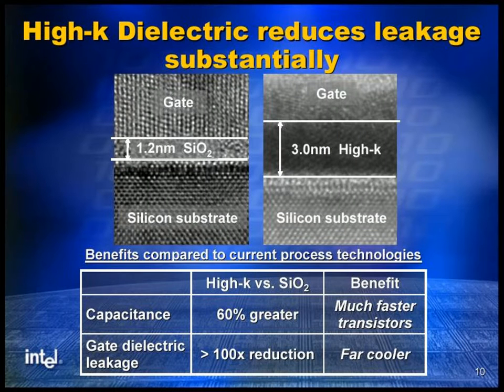What happened, actually we already discussed it. The main thing that happened that was not yet there in the document of 2001 was this introduction of the high-K dielectric process. And you see the situation from a thickness of 1.2 nanometer of silicon oxide.